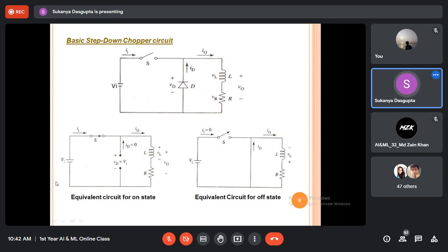And in order to implement that thing, definitely the polarity across the inductor must be reversed because V is equal to L di/dt, or we'll apply here Lenz's law, which is showing that the voltage developed is just opposing the cause of it, which is the current, right? So here definitely the voltage across inductor will be reversed. So previously this is at positive polarity, now this is at negative polarity.